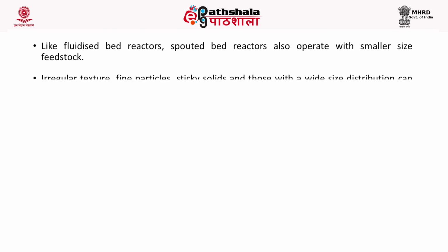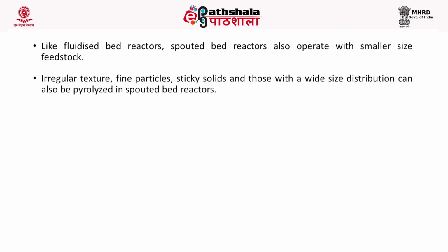Like fluidized bed reactors, spouted bed reactors also operate at a smaller size feedstock. Irregular texture, fine particles, sticky solids and those with wide size distribution can be pyrolyzed in spouted bed reactors.